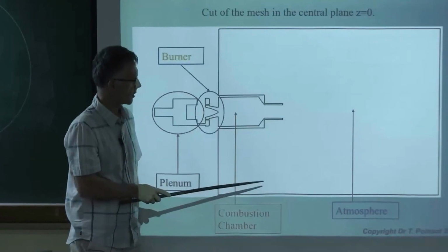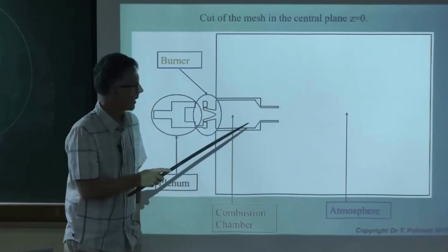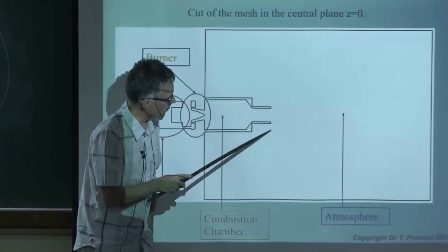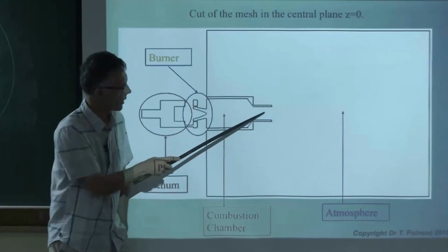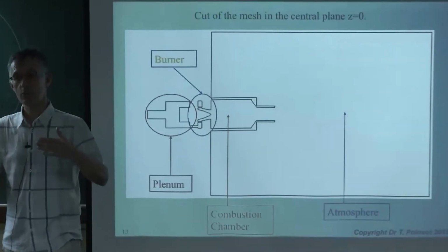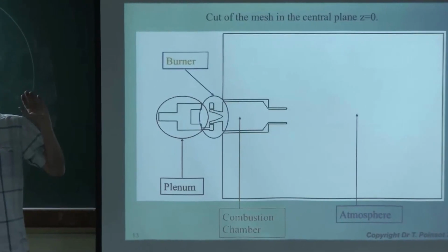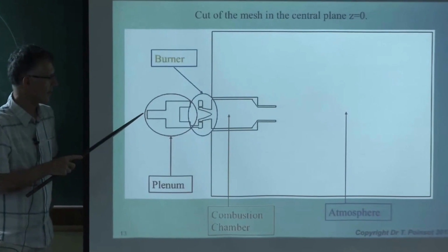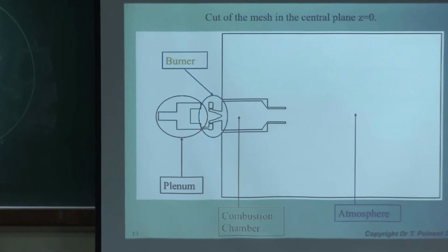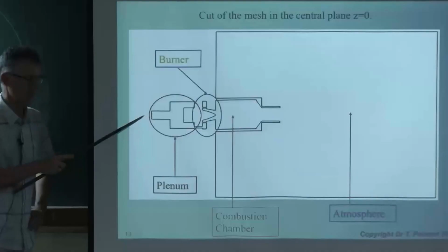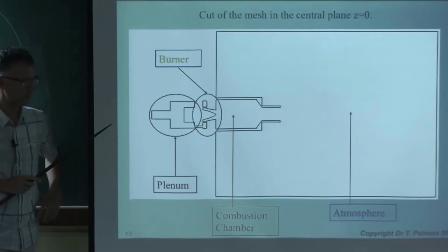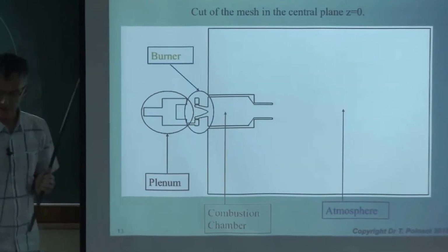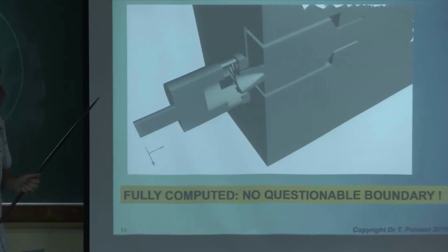Okay? So the atmosphere is meshed, and if you have an unstructured code, it costs you nothing. You put a few big meshes here, you get some refined zone here, and that's sufficient. And this way, you don't have to worry about the outlet impedance. There is one, but it's captured by the code. No problem. The inlet here is more tricky because we don't exactly know. DLR told us there's about a 10 meter line here. And so the inlet impedance is tough. Here we suppose that the flow rate was imposed. And that's the only two conditions you have: outlet pressure, inlet velocity, or atmosphere, flow rate, excuse me.